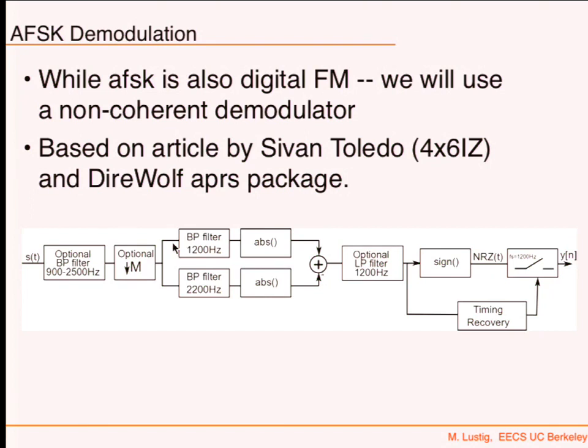And they're going to switch between each other at a rate of 1200. And because the rate is 1200, then that will be a good filter. Now, we're supposed to see something which is really square, but after this filtering here, it's not going to be square. It's going to be more smooth. So it's, again, a trade-off between noise rejection and keeping the signal. If you have square, that has higher harmonics, right?